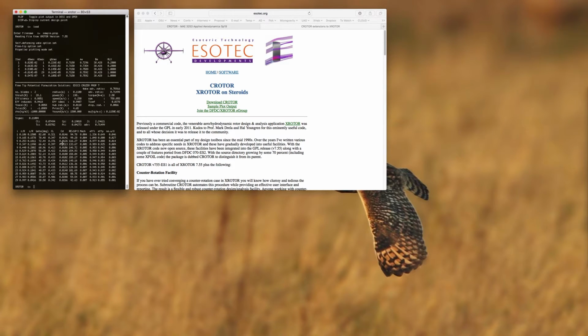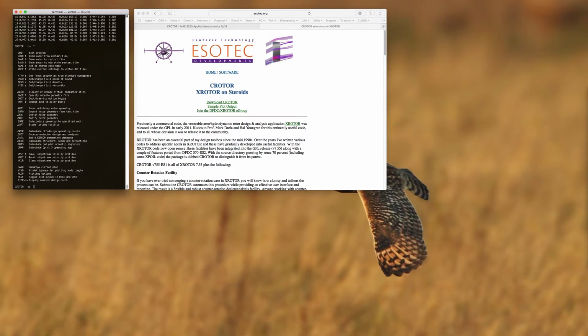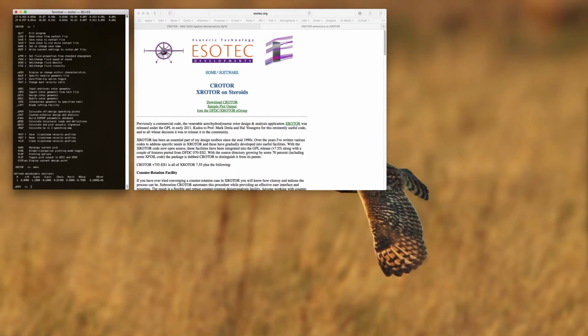So we're not going to use this particular propeller. We'll upload some others so that we can take a look at those. Before we do that, there are a couple other kind of menu commands that I want to go over. First of these are airfoil characteristics. So every propeller is going to have a basic set of airfoil characteristics that you're going to define the propeller around. And most propellers are going to be blended. They're not going to have a single airfoil characteristics across the entire prop.